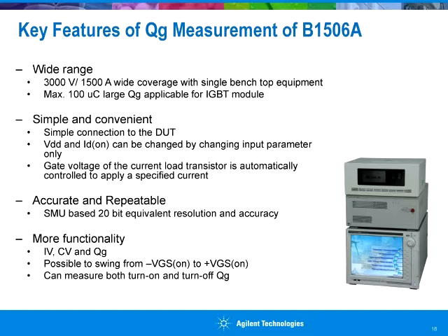With this large coverage, the B1506A can measure QG of big size IGBT modules. For example, the coverage of QG is 100 microcoulomb. It's very big.